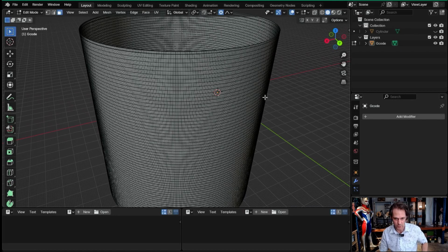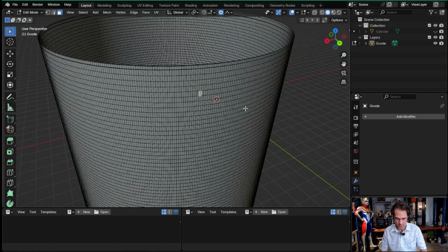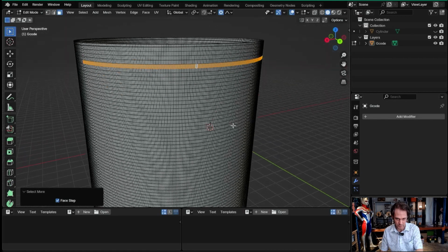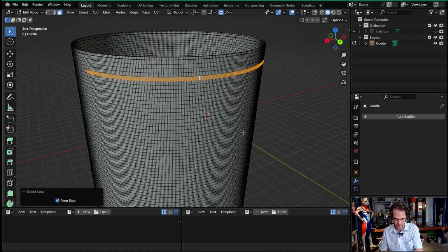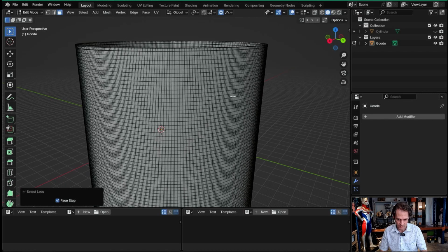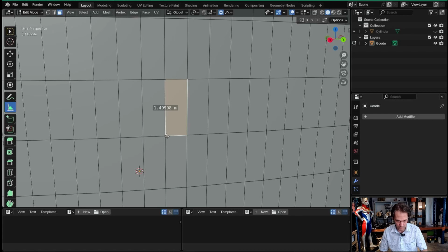When you import from Nozzleboss into Blender, it creates the Gcode represented by a single extrusion of faces. You see here, when I expand the selection, it's expanding only on a single line, so it's not a solid surface, it's a spiral going all the way up. So this is the toolpath created, and if you measure the height, it's 1.49.